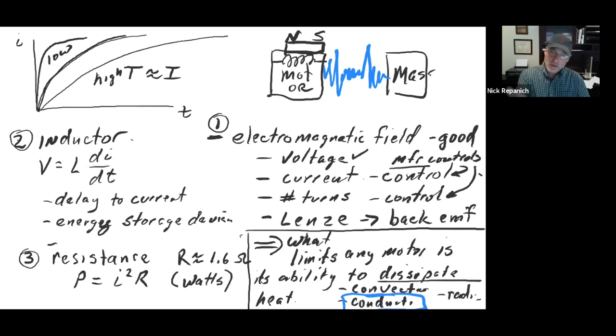And so you keep that in mind as you are just setting a motor on your bench top and messing around with it. How much conduction's going on? Zero, right? You're relying on convection. So you're really going to heat up motors fast just sitting on the desktop while you're working on it in your proof of concept systems, because you're not applying any conduction. And that's how they're really supposed to be used for the most part, okay?